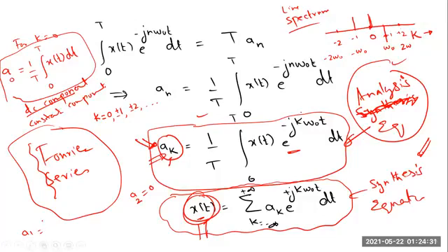Most of the time you will be looking at a signal in time domain. So you plot your signal with respect to time. That is the time domain representation of your signal. But Fourier series allows you to represent a signal in frequency domain. And sometimes frequency domain information is more important for us. So whenever you are interested in frequency domain analysis of a signal, you have to use Fourier series tools.